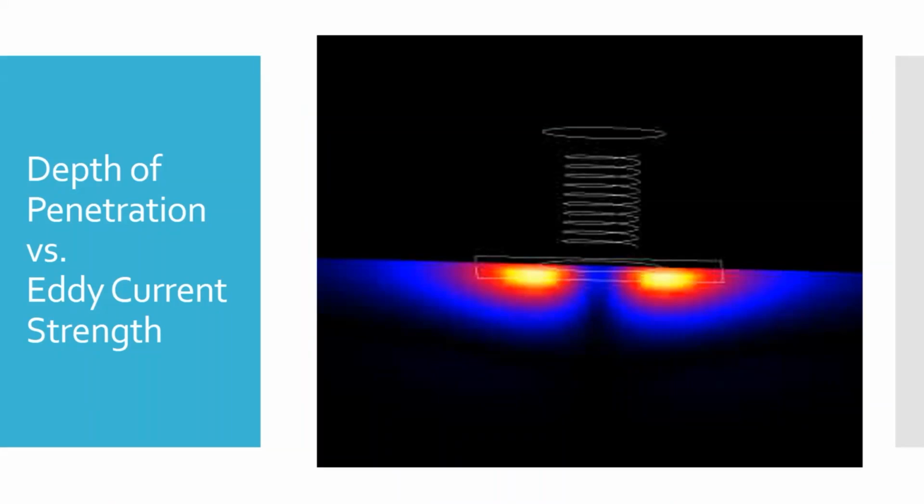So really, in this case, you can see the eddy currents are forming to the left, to the right of the probe, as well as ways below it. But really, the depth of penetration in the area that you're actually looking at right now is pretty much directly under. It's kind of the orange and red areas right there. That's about all you're seeing right now on the probe.